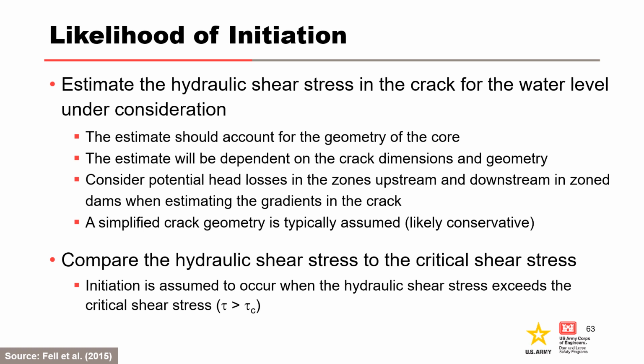Once the hydraulic shear stress has been estimated, it is compared to the critical shear stress, which will initiate erosion for the soil in the core at the degree of saturation of the soil on the sides of the crack.